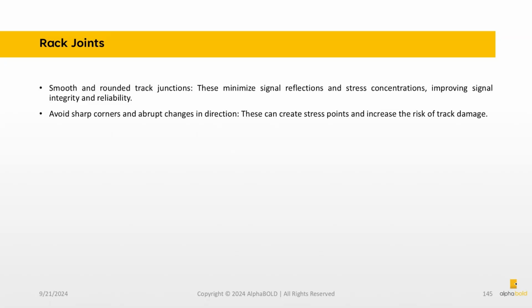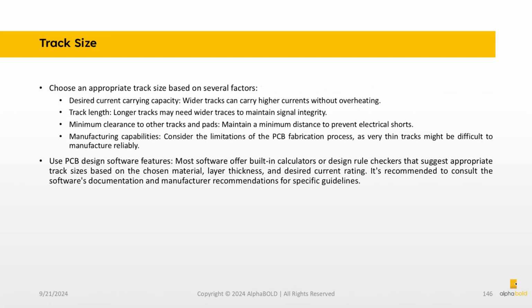Avoid sharp corners and abrupt changes in direction. These can create stress points and increase the risk of track damage. Choose an appropriate track size based on several factors. Desired current carrying capacity. Wider tracks can carry higher currents without overheating.